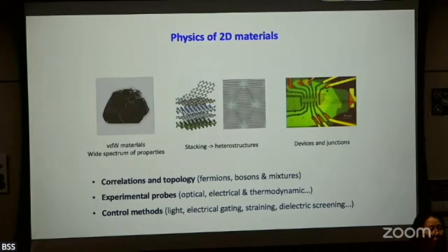Electrical transport measurements are pretty straightforward, because of the early development of microstructures. But you need to figure out how to put the contacts on. So for graphene, it's relatively easy, but for semiconductors, usually that's challenging. The reason is because you have a band gap. If you want to put a metal on it to avoid the Schottky barrier, you need to find the appropriate material to get good ohmic contacts.